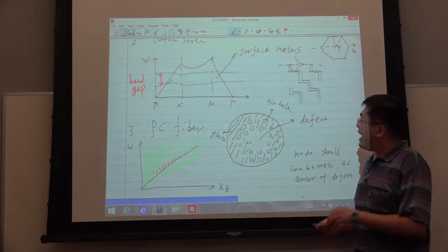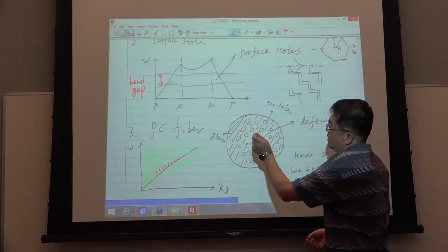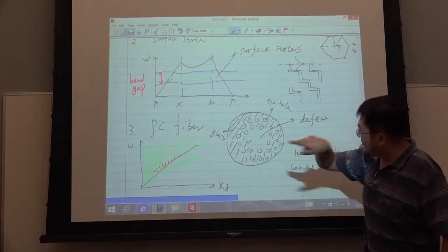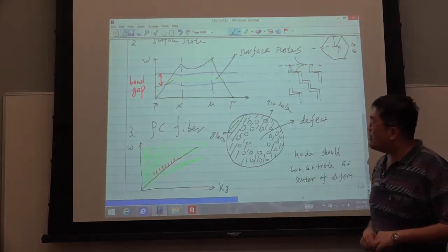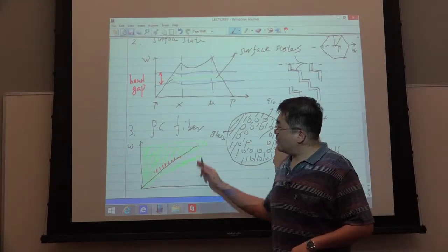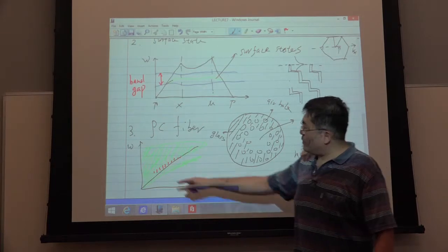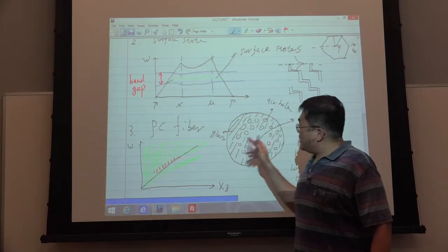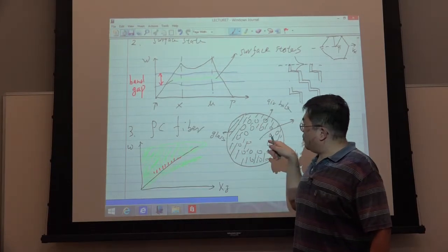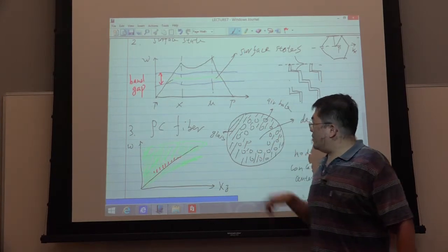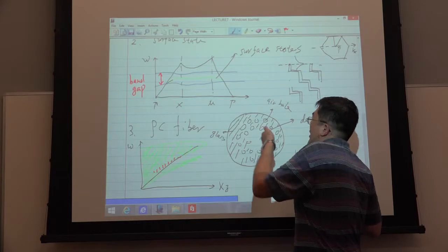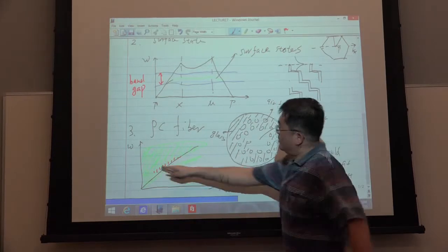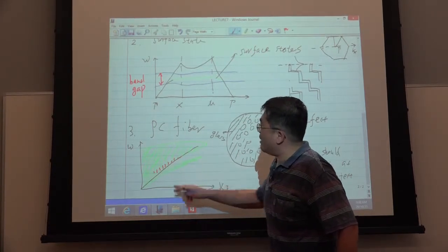Because this is photonic crystal fiber, Kz, I mean the propagation vector along this direction, should not be equal to 0, because the wave should propagate along this photonic crystal fiber. Okay, then we can draw this dispersion relation. So the region we use is the red region. Why? First thing, Kz cannot be too large, because they have a propagating wave along this direction. Another thing, they should be confined because of this band gap. The white region is band gap.